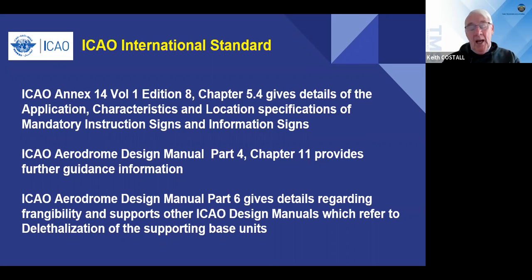And when we delethalize, that means that should an aircraft leave the pavement for whatever reason and hit our guidance signs, those guidance signs will break and not damage the aircraft. But because these aircraft are heavy, when leaving the pavement their wheels and undercarriage may dig into the ground. And therefore, when those wheels dig into the ground and then hit our guidance sign, the first thing the wheels are going to hit are the bases. So we have to chamfer the bases.